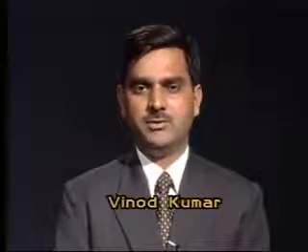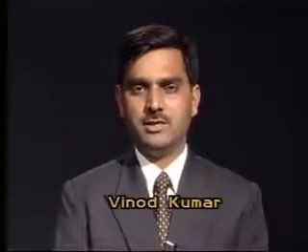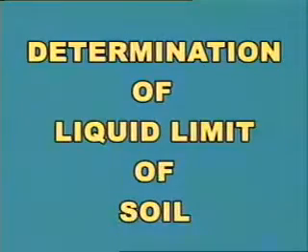Hello viewers, the liquid and plastic limits of soil depend on amount and type of clay in a soil and form the basis for soil classification system. The liquid limit of a soil is the minimum water content at which the soil is still in liquid state, but has a small shearing strength against flowing, which can be measured by standard procedure. In this program, we shall demonstrate the determination of liquid limit of a given soil.